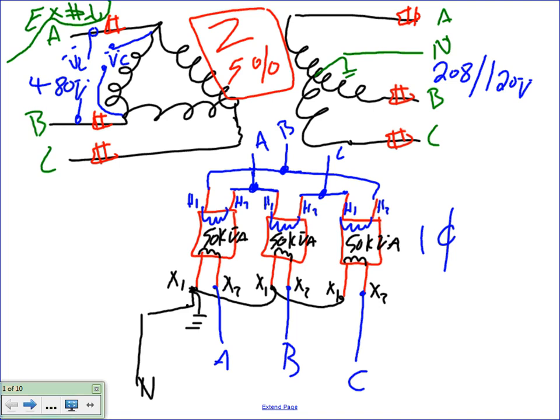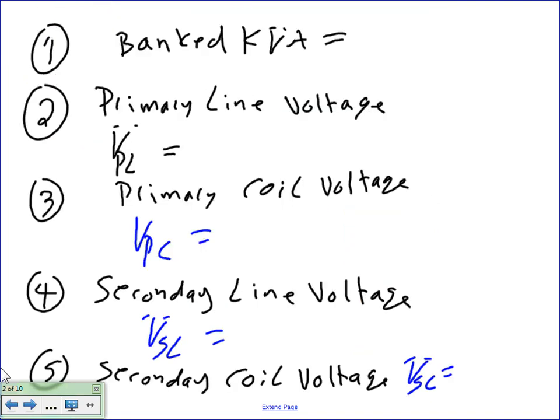Okay. Before I move on, everybody knows that each one of these is 50 kVA each, and we're banking them. They call it a banked system. Bank them to make a three-phase system. Cool. You would rarely see this in a commercial building; in industrial it's common. Utilities do it all the time. Okay, so that's basically the first step.